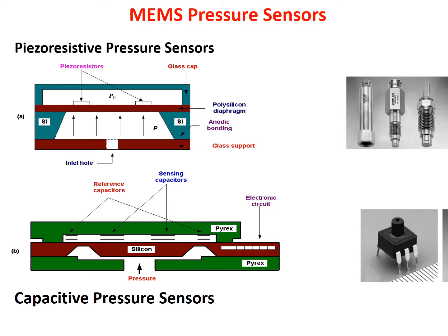And if you remember, how we can generate the piezo-resistive layer, we can use the doped polysilicon, right? You remember? So that doped polysilicon can act as the piezo-resistors, and they are of semiconductor type, and as we said, semiconductor type strain gauges or piezo-resistive materials have a high gauge factor, and because of the high gauge factor their sensitivity is more, right? So here, just for representation purposes, two strain gauges or piezo-resistors are shown. You can similarly use another two at the bottom sides as well, to improve the sensitivity further, right?